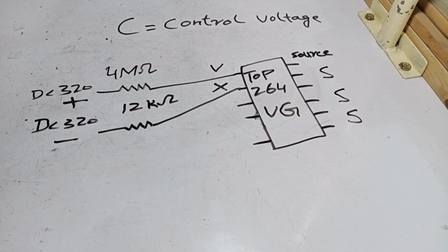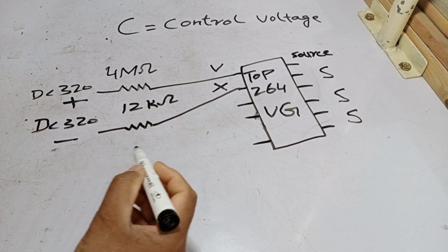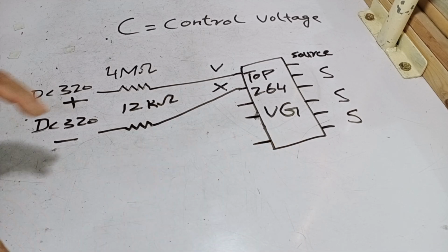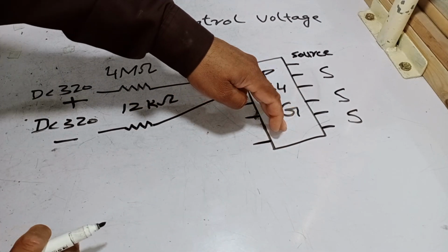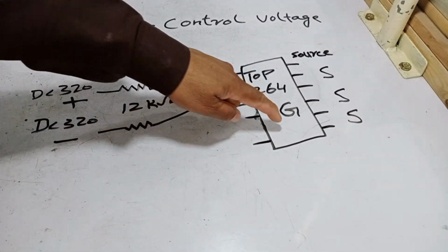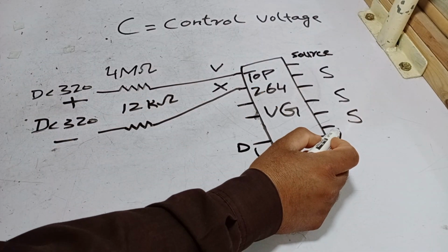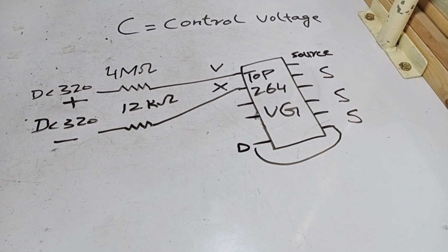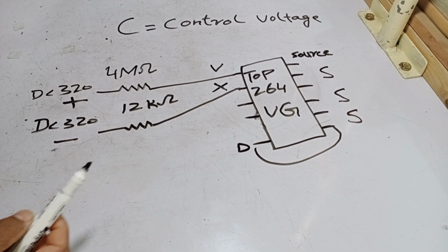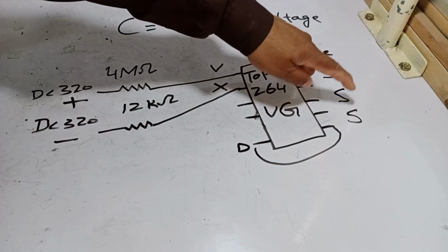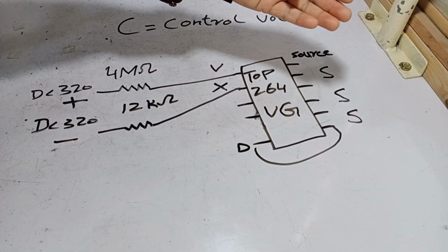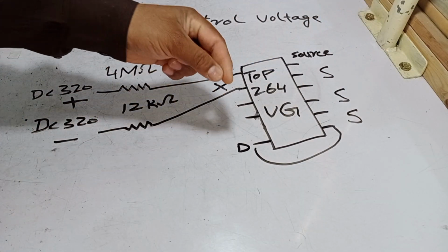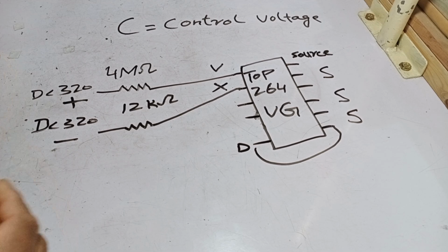When the system is powered on, it generates 320 volts DC. After generating this voltage, the switching IC uses its internal system, which includes a preset timer. Here's how the process works. The timer connects the drain pin directly to the source pin in series for a brief period. This allows the downstream system, such as the chopper, to turn on and start generating the required voltages. However, all of this happens within milliseconds, so it's not noticeable to us, but the process is actively occurring internally.